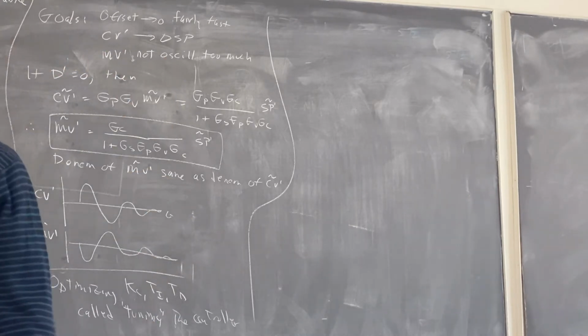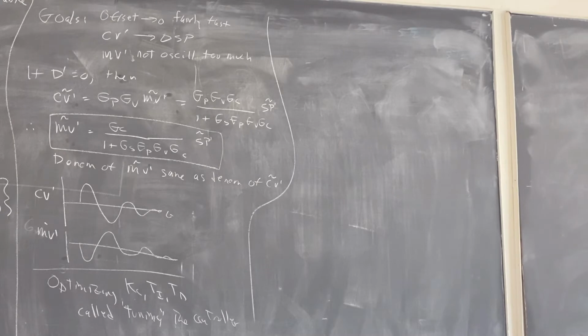And if we're stuck with a PID controller, which is not a bad situation to be stuck with, how do we find them? And again, you can't really do this analytically unless you're in that special situation where you could analytically have a good model for the integrated absolute error as a function of these things. And then you would take the partial derivatives with respect to these three values, set them equal to 0, and solve those simultaneously. Sometimes that's possible.